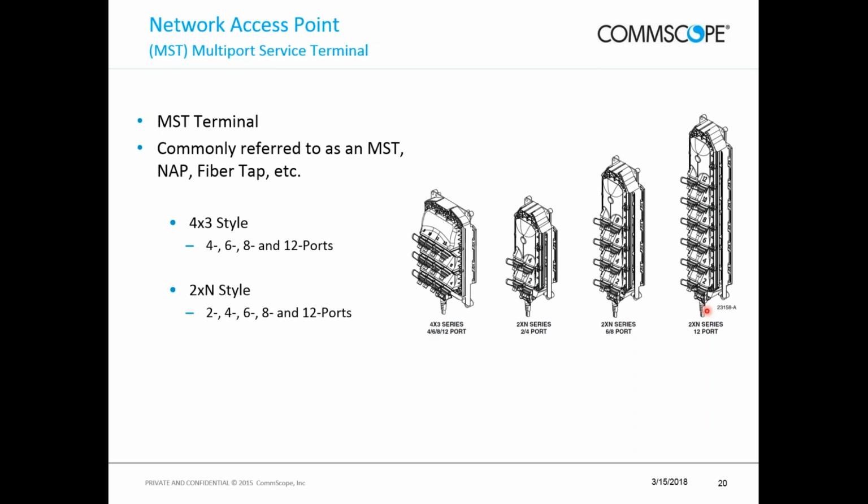Yes. Now I will add one other scenario that's much more common, and that is a technician accessing this MST and trying to plug a hardened drop connector into it who hasn't been trained, and has somehow unintentionally damaged the optical connector inside the device. In this case, it's not as bad, because it's not like a dig up where, in this example, all 12 customers were knocked off of service. We'd only have one customer where the installer damaged the connector.